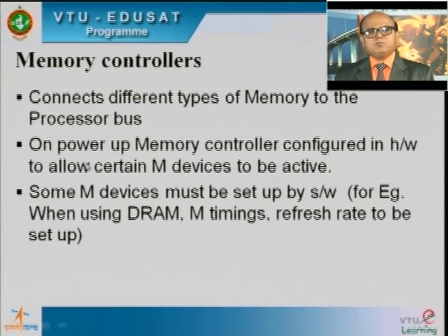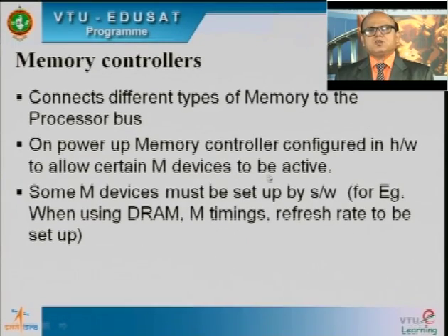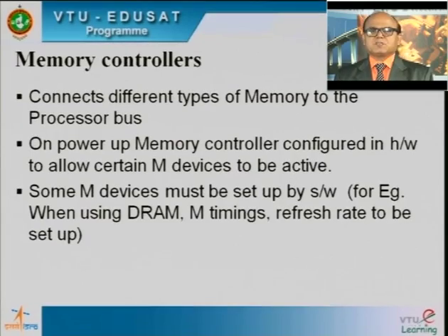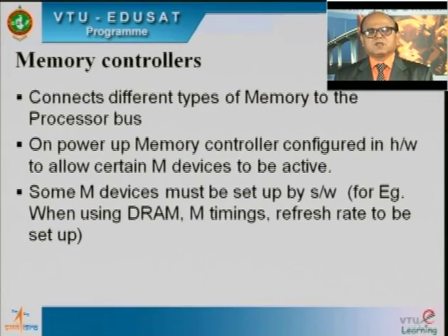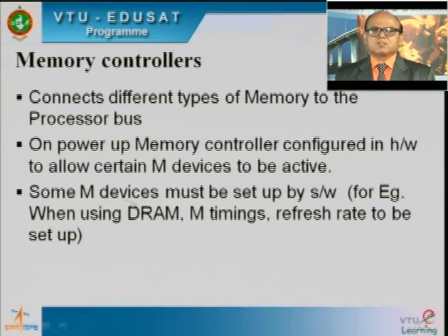And every time after a power up, that means when the processor bus is switched on, the memory controller is configured in hardware to allow certain memory devices to be active. Some memory devices must be set up by software. That means every time after the power up, it is necessary to configure some of the devices, which is done by the memory controllers.